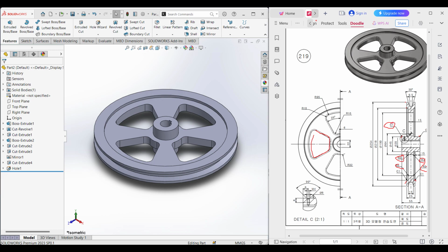But in this portion and this portion, we don't see any fillet radius, but we can see they also have a fillet. If I give the same fillet of 3, it doesn't match the chamfer, so I'll give a smaller fillet here. I'll give a 1.5 unit fillet, or you can give your fillet as you want.